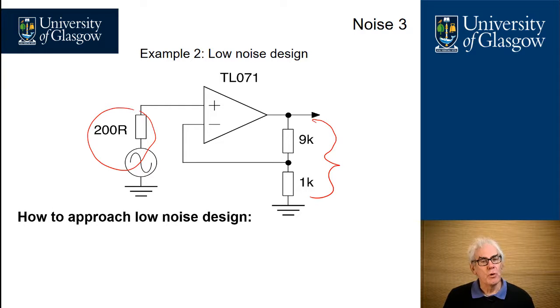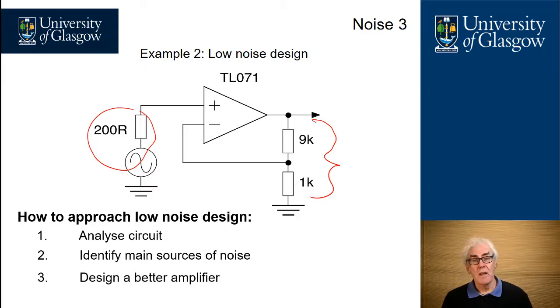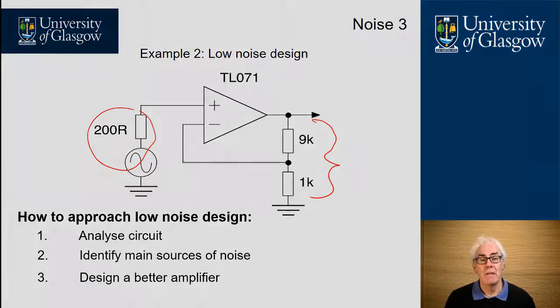Revising how we approach low noise design. First thing, we analyze the circuit. Secondly, we identify the main sources of noise that are occurring inside that circuit. And thirdly, we try to reduce the main sources of noise to design a better amplifier circuit for the application.